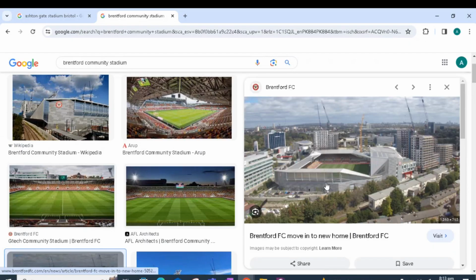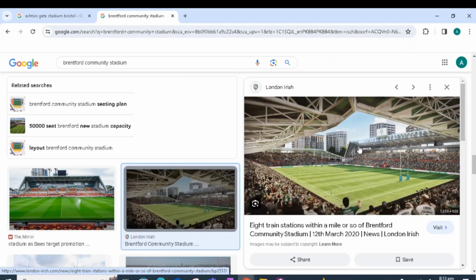We will now discuss another stadium called Brentford Community Stadium. This is also a football stadium shown over here. This stadium has got steel cantilever trusses stacked one behind another all around the stadium. The cantilever trusses are joined with each other by straight members. There is also a steel truss connecting all the cantilevers around the stadium.